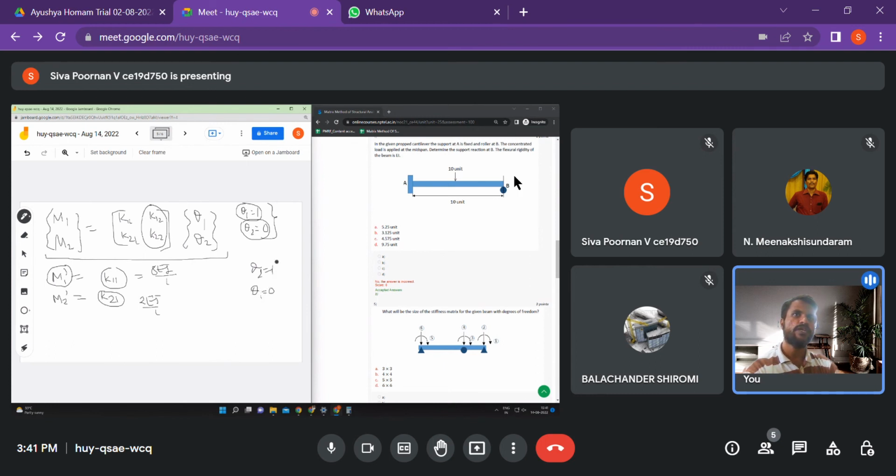Basically what I'm doing by substituting these things is decoupling. If I put one thing as 0, then it will become decoupled, right? So by decoupling it I'm finding these values. Once I find those values, I now know the relation between m1 and m2. Just like how I had only one stiffness value, now I'll be having a matrix. This matrix will become known to us, right?